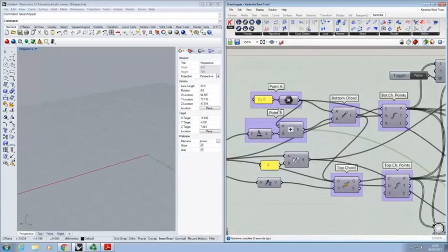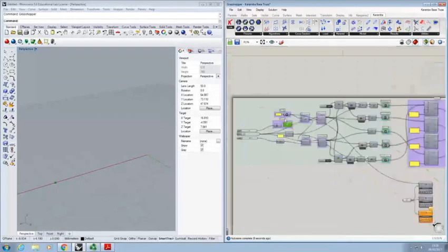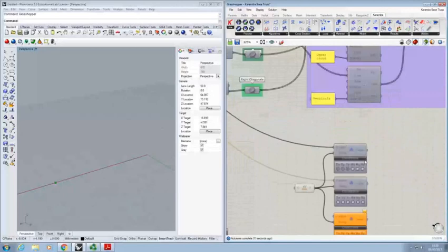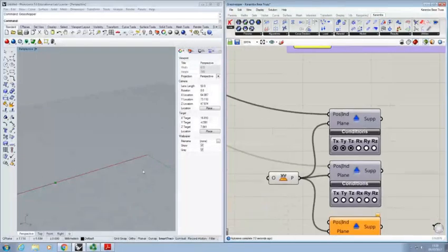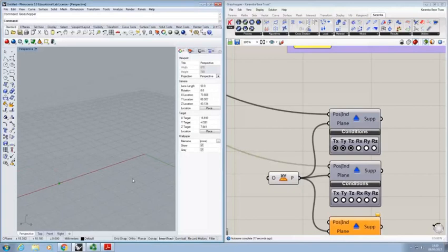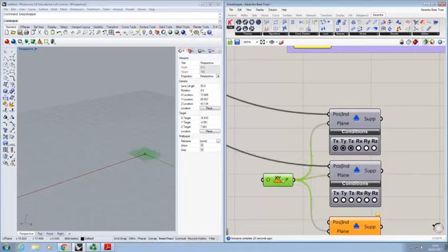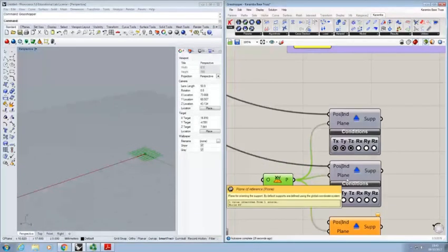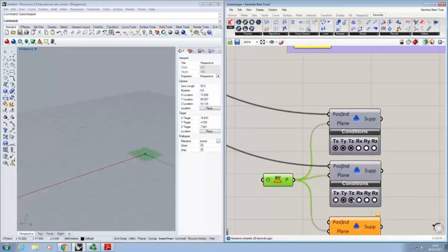Point A is restrained in 3 directions, point B, the other end, is restrained in just 2. If we have our XYZ global coordinate system matched with the local coordinate system here, XY, we know that we need to restrain Z and Y. So TY and TZ.